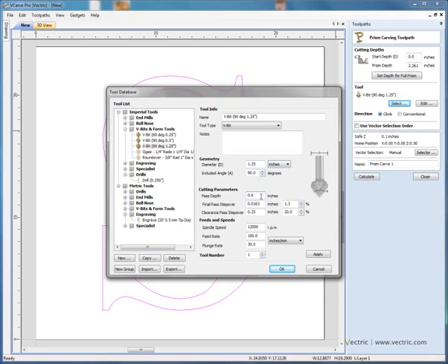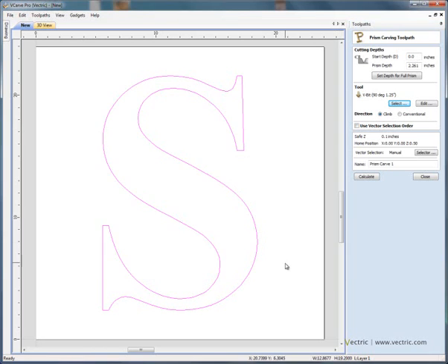And this assumes that we're cutting relatively soft materials, and these letters will often be cut out of sign foam, which you can run the router into very quickly, and they're relatively easy and fast to cut. We've also got some options here for clearances. So clearance pass step over, let's make that quite large, so 0.5 inch, and a finishing pass step over, we'll make that say 20 thousandths. We also on this page would specify the step overs and the speeds and feeds for the cutter. And if we say apply, click OK to select that cutter.